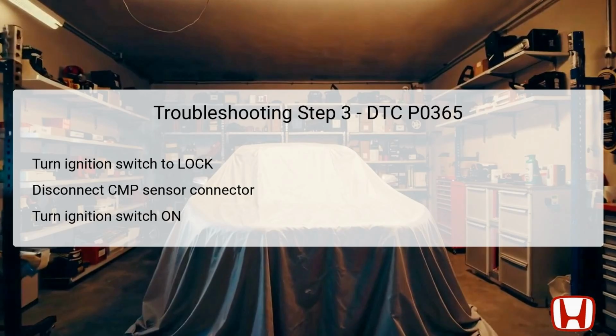This disconnection and power up will allow you to test the sensor circuit effectively while assessing the voltage levels necessary for proper sensor function. This step is critical in isolating the sensor itself as a variable in the DTC diagnosis.